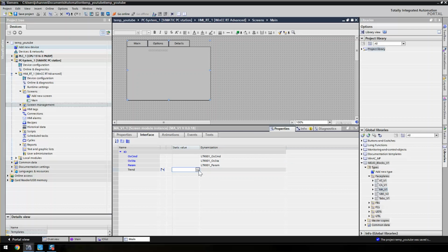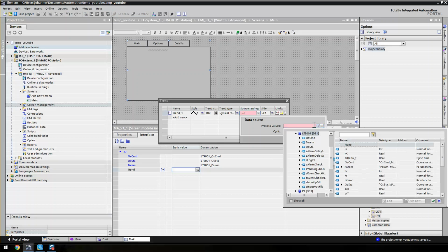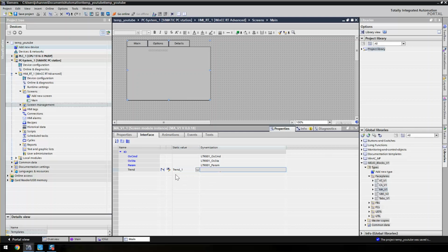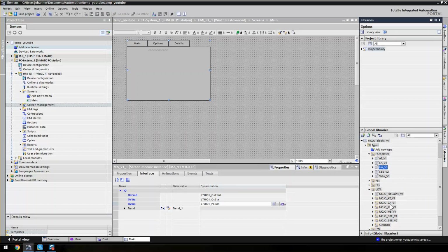And this little treat, what do you want to trend? You would like to trend this guy. You can also add more to it, like limits, but that's the only difference from the approach that we used in TwinCat. Still exactly the same. This is allowed if the UDTs or DUTs, whatever you want to call them, are in the same library as your faceplates. If you want to make your own, just make sure that the DUTs are in the library.